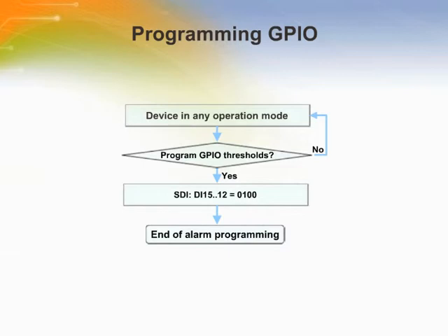The device refreshes the GPIO data on every CS falling edge as per the SDI data written in the previous frame. Similarly, the device latches GPI status on the CS falling edge and outputs it on SDO if GPI read is enabled by writing DI04 equal to 1 during the previous frame, in the same frame starting on the CS falling edge.